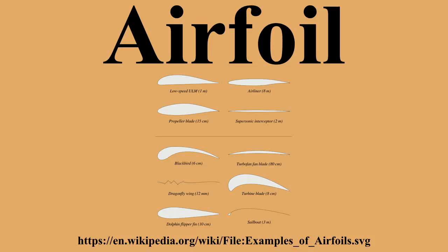The drop in lift can be explained by the action of the upper surface boundary layer, which separates and greatly thickens over the upper surface at and past the stall angle. The thickened boundary layer's displacement thickness changes the airfoil's effective shape. In particular, it reduces its effective camber, which modifies the overall flow field so as to reduce the circulation and the lift. The thicker boundary layer also causes a large increase in pressure drag, so that the overall drag increases sharply near and past the stall point.